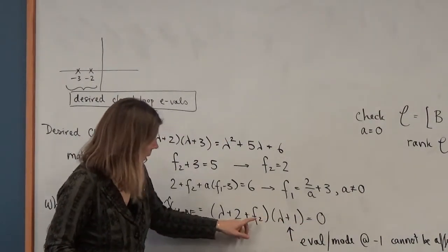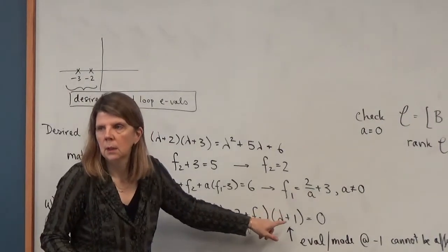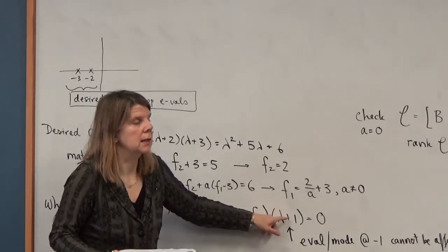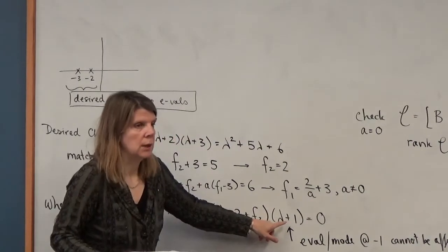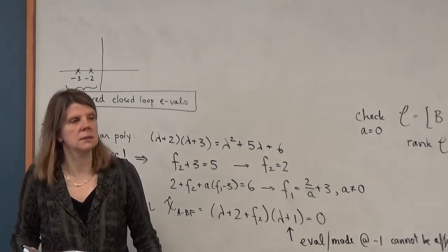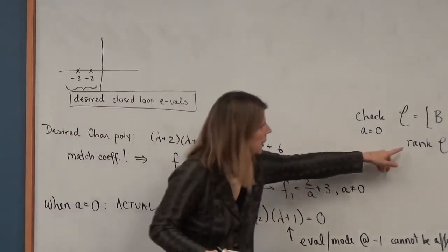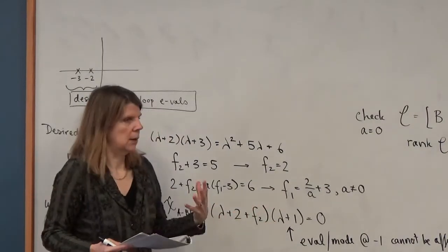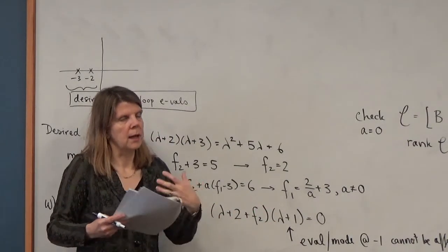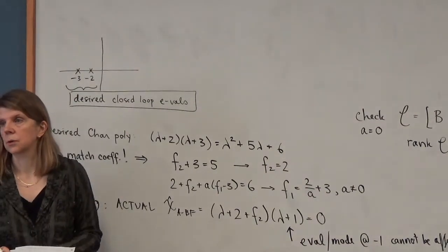And you can see that loss of controllability and the loss of ability to shift that eigenvalue, which was at -1 for the open loop system. It's got to stay at -1 now. State feedback isn't going to shift that eigenvalue. So the rank of the controllability matrix tells you about the dimension of the subspace of R^n that you're able to actually control.